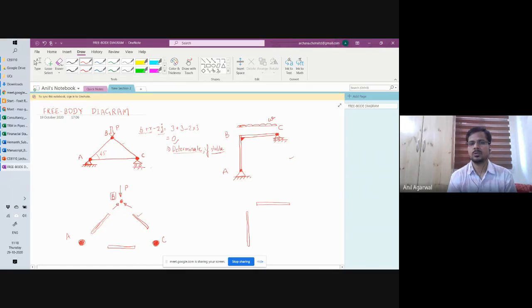So if the two forces are equal and they are acting at equal angles, that is 45-degree angle, horizontal component will automatically cancel each other out. The vertical component of each one of them has to be P by 2. Okay. So that means this force has to be P by 2 multiplied by root 2, right? If this is the force, its vertical component will be P by 2. Agreed? I'm not making a mistake here, right?